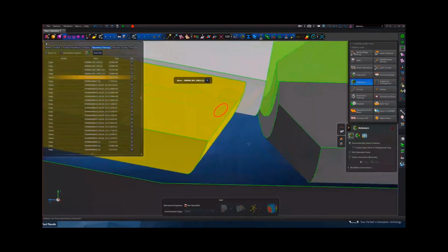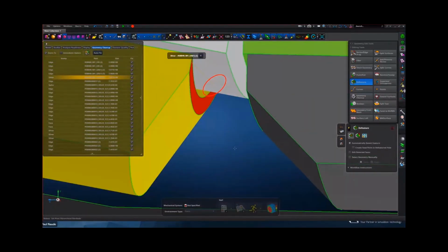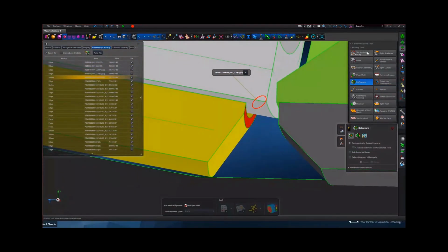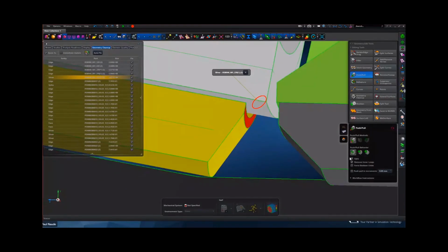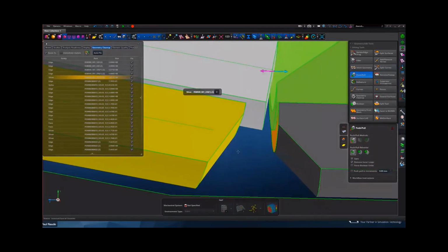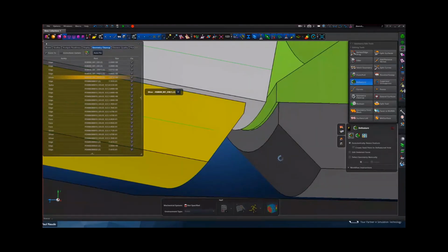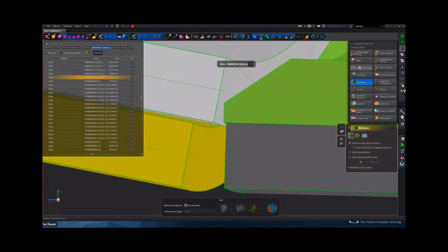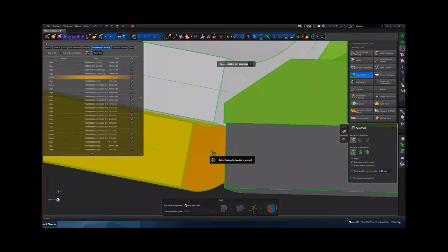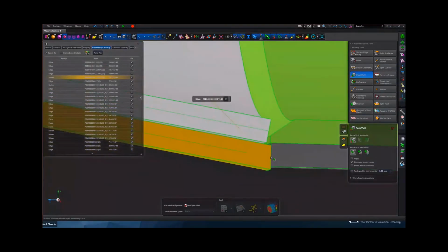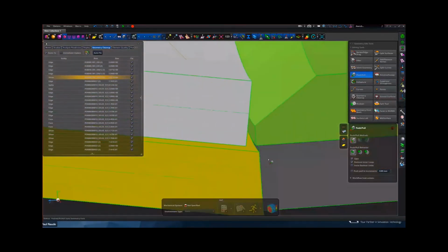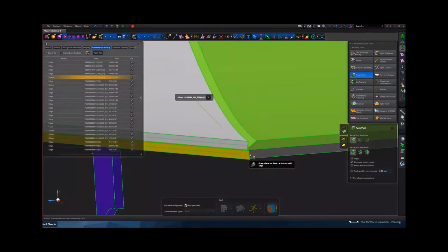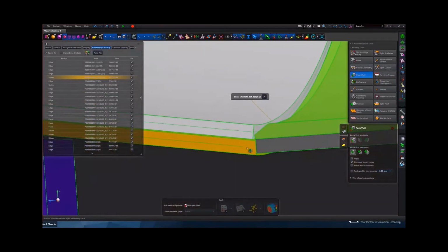Again, here we see two solids that are not facing, probably because the original CAD drawing is leaving a gap for welding assembly purposes, but obviously if you run a finite element model, we can't live with that. So one way is to just get rid of the chamfers first. I can put it back on automatic, get rid of that, and use our push, pull, and up-to tools to quickly get rid of those ones there. Okay, there's obviously a little offset there. Depending on what the purpose of your analysis is, you may or may not want to get rid of that.